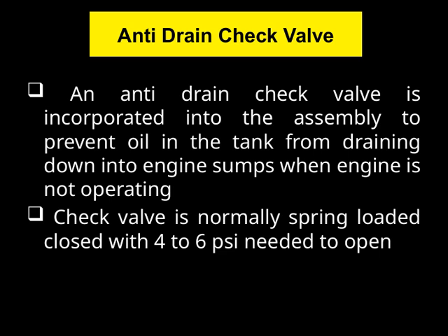The check valve is normally spring-loaded closed, which means it stays shut under normal conditions. It requires about 4 to 6 pounds per square inch of pressure to open, allowing oil to flow when necessary. This design effectively prevents oil from flowing back into the engine when it's not running, contributing to the overall reliability and efficiency of the lubrication system. So, in essence, this anti-drain check valve plays a key role in maintaining proper oil management and protecting the engine's health.